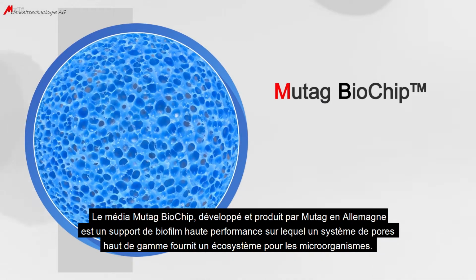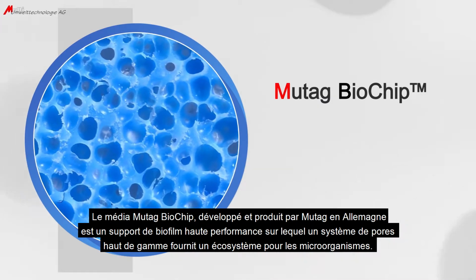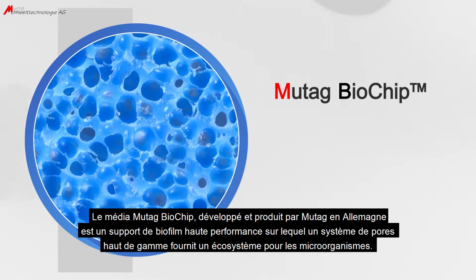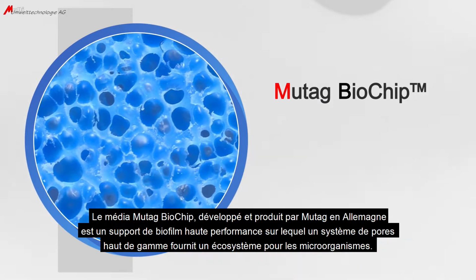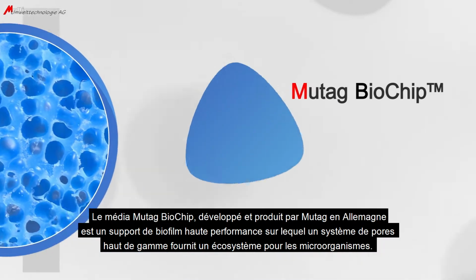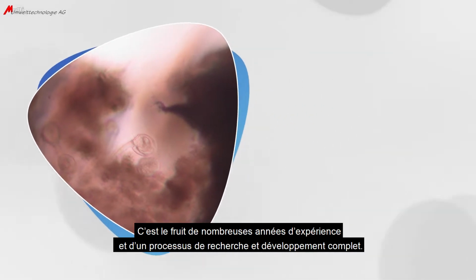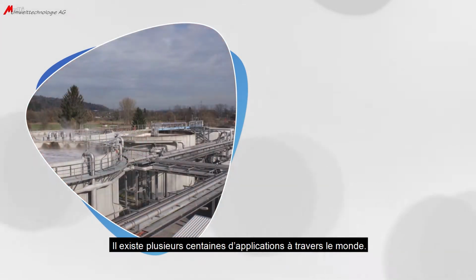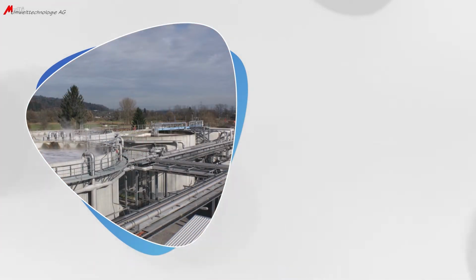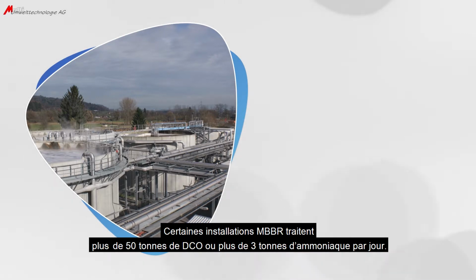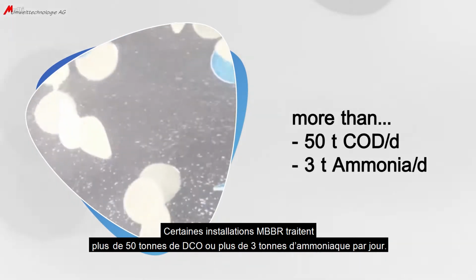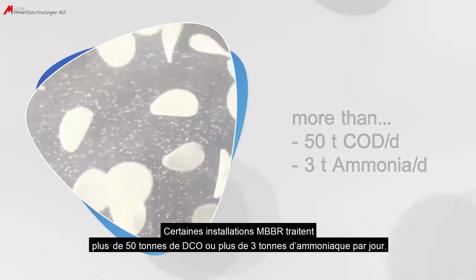The Mutag BioChip, developed and produced by Mutag in Germany, is a specially designed high-performance biofilm carrier with a high-grade pore system which provides a habitat for microorganisms. It is based on experience and extensive research and development. There are several hundreds of successful applications worldwide. There are MBBR plants which are treating more than 50 tons of COD per day, or more than 3 tons of ammonia per day.